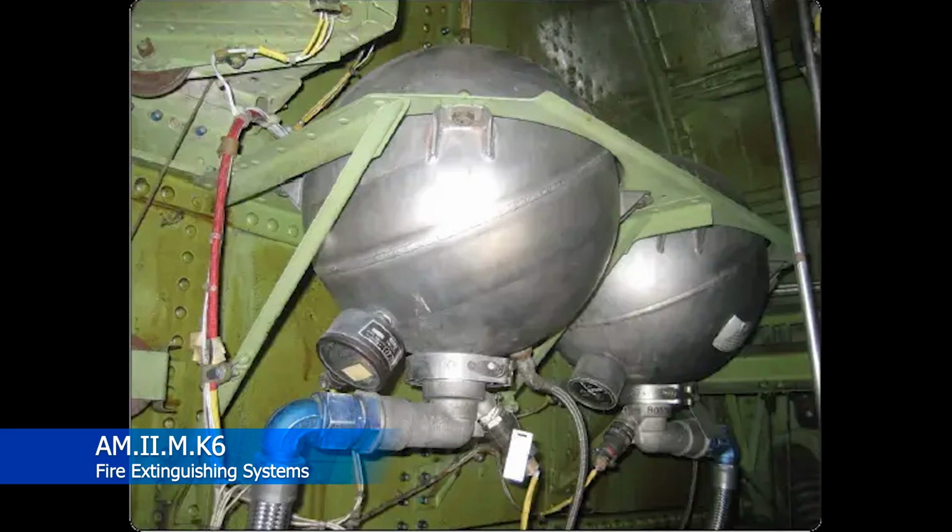Then you have the cargo and baggage compartments, where we have the least amount of control on what goes onto an aircraft. So you're going to have a high likelihood that you have some sort of fire shenanigan happening in there. And then next is lavatories, because people will smoke or they'll pour something into the trash can that might spontaneously combust with something else that's in there. You have all kinds of possibilities of fire. So those are the four places you're going to have fire suppression systems installed.